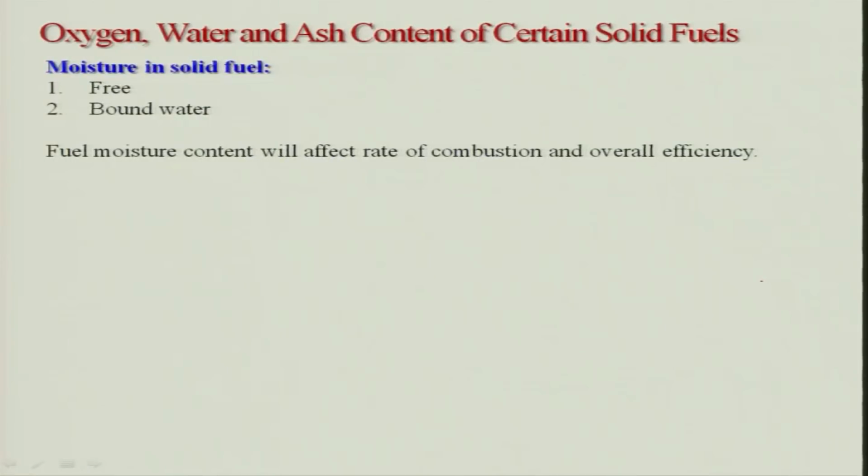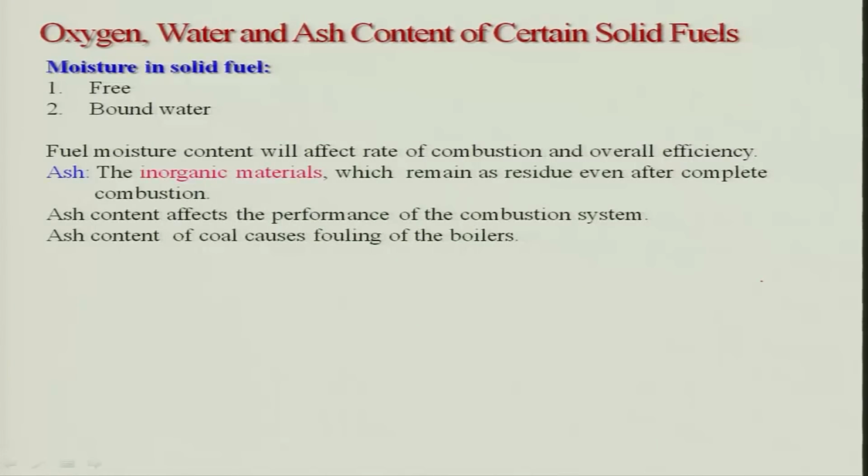Let us look at basically oxygen, water and content of certain solid fuels. Basically moisture will be free and bound. Free means if you just vaporize it, it will go away. Why are we concerned about moisture of solid fuel? Because it will affect the rate of combustion and overall efficiency. First of all, you have to supply an amount of energy so that it will vaporize, right. Besides this, if it is there, then it will hamper the combustion from taking place, right.